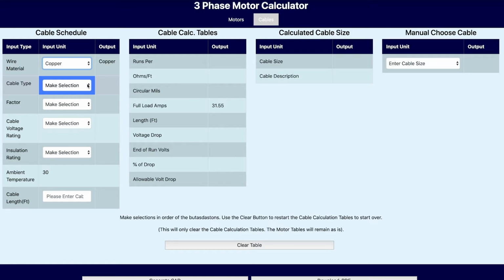EDM allows the user to choose between single and multiple conductors and the different derating factors depending on the cable installation method. This allows the user to analyze the different options and make the best choices for the motor design.